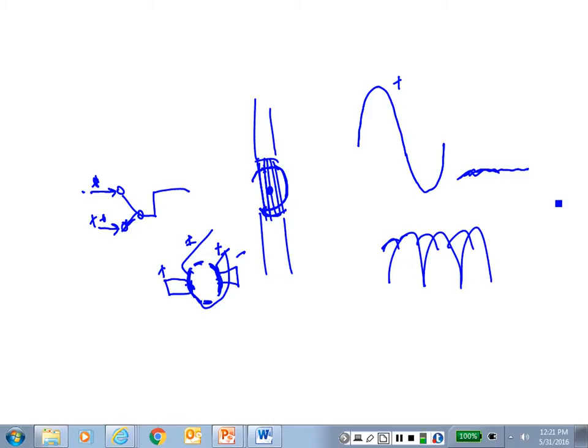It's just that you'll have a little ripple up there on the switching, and that's not really true. The way the thing works is that it actually is between two segments at the same time. If you ever looked at a brush, it's actually looking at two segments at the same time. So basically, it puts out a really nice DC. And what determines the amount?